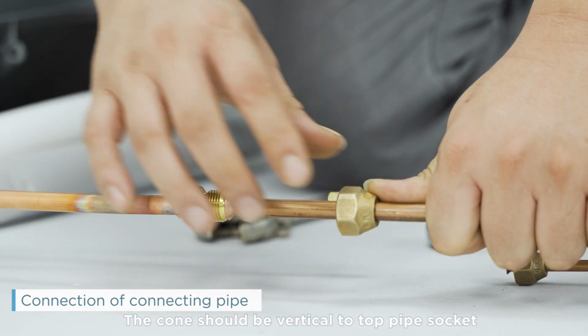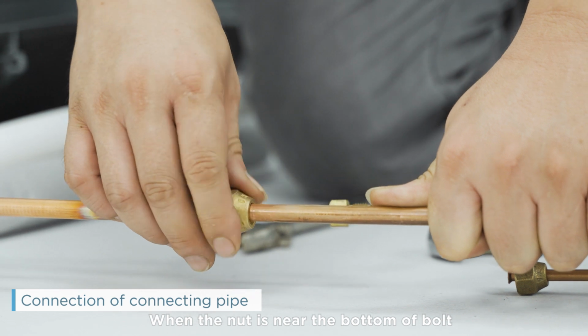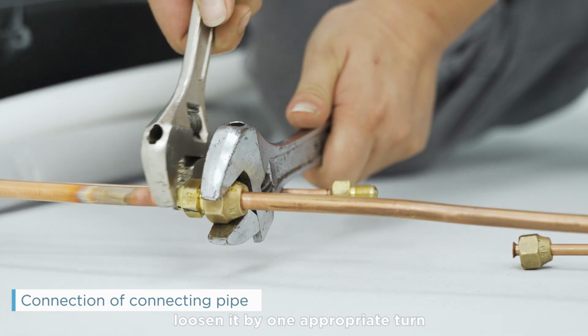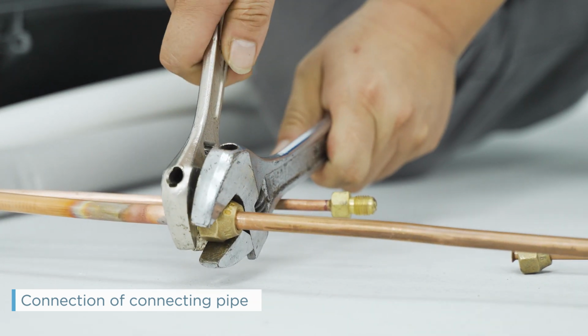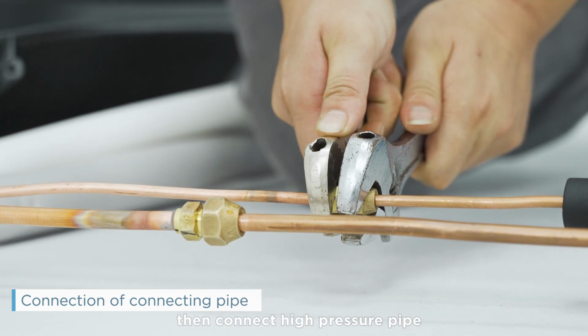The cone should be vertical to top pipe socket. When the nut is near the bottom of bolt, tighten it with wrench. After tightening, loosen it by one appropriate turn and then tighten it again. Firstly, connect low pressure pipe, then connect high pressure pipe.